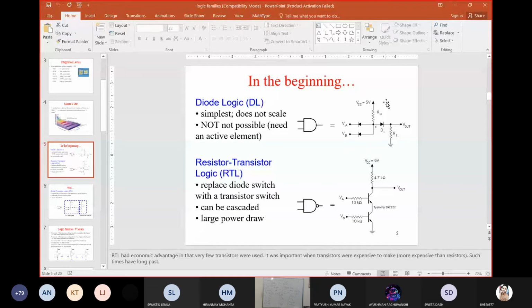See, don't check the slide. What is written there? Don't check. You just see the circuit only. If for the other cases it is not working, can I say this is a simple circuit for the AND gate? It's wrong. Don't you think so? What is the alternative you can suggest? You tell me. That means with this diode logic, I can't develop an AND gate.